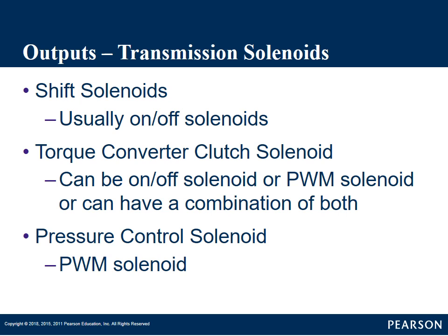The one I'm thinking of is the 4L60E. In those early days when they went from an on-off solenoid to a pulse width solenoid, in the first ones they just added that pulse width solenoid and kept the on-off solenoid, I would think as a cost saving issue. They didn't have to redesign a valve body if they did that. They later redesigned the valve body and the transmission a little bit, so then all they had was just the pulse width modulated solenoid. But there are some cases where you have both.